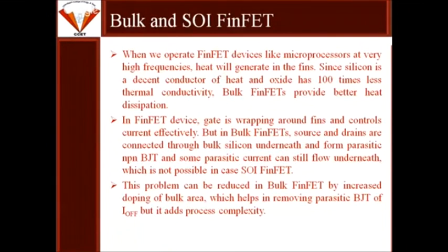So we have seen one advantage of bulk FinFET and then another advantage of SOI. This problem of bulk FinFET can be reduced by increasing the doping of the bulk area, which helps in removing this parasitic BJT, but it adds process complexity.